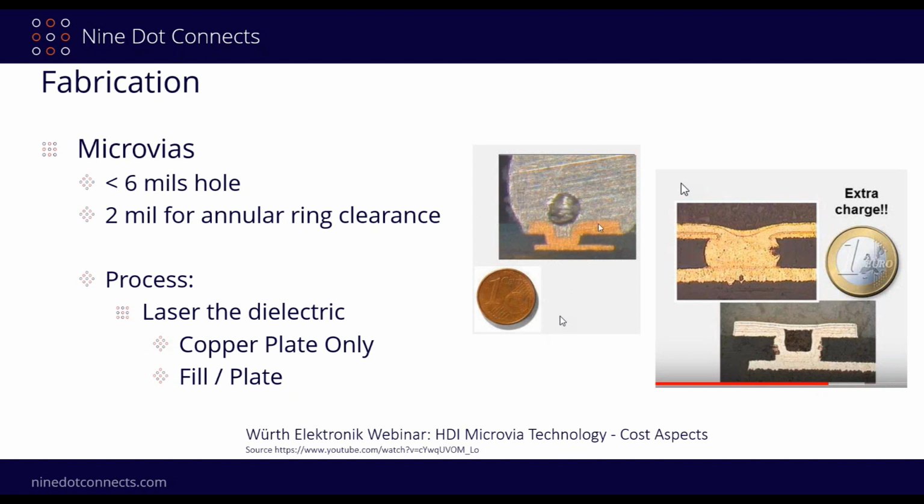However, it depends on your reliability again, because what will happen over here is this is the end product, and what they did is they sliced through it, and what you're seeing here is an air bubble, which makes all the sense in the world, because when this solder bump was probably put on top of this at the very beginning, there was air all around it. There was air in the gap, there was air near it, and so when it started to melt, all of a sudden that air started to rise, right? So now you've got a bubble over here, but then it hardened fast enough to trap it.